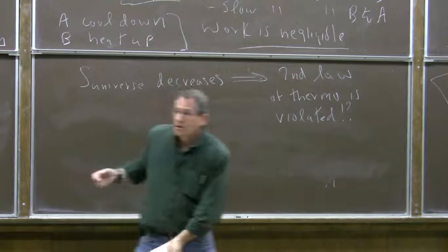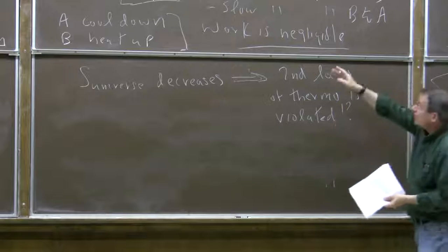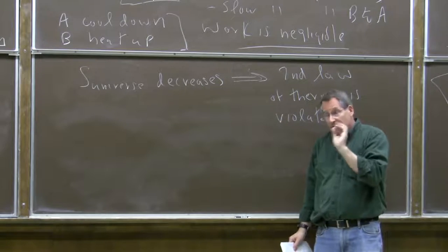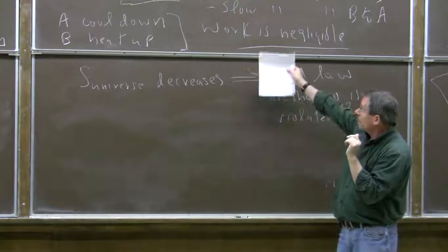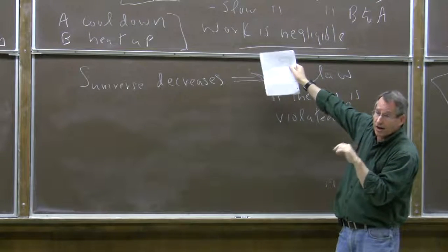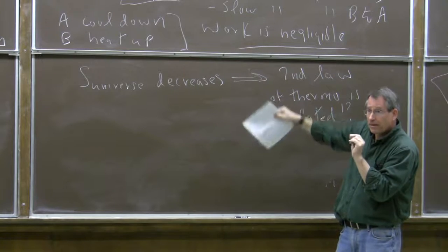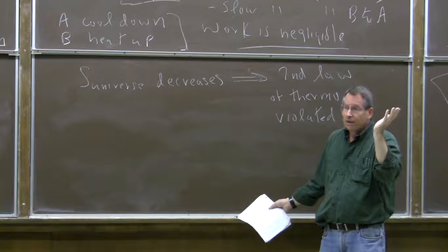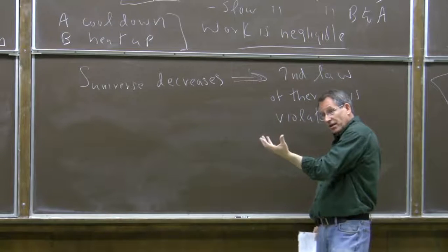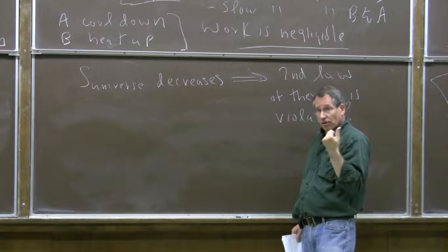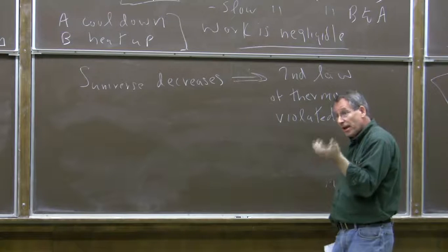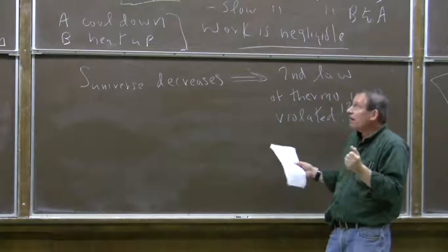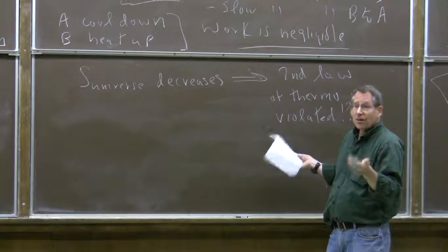Oh, yeah, right. So they're bouncing around, right? Every once in a while, if I keep the door closed, they're going to bounce where the door is. Instead of letting them bounce, I either let them bounce if, coming from one side, they're too hot, or coming from the other side, they're cold. Otherwise, I let them through. That's going to cause some flow of heat from one side to the other, right? One side will get hotter, the other side will get colder. Second law says you shouldn't be able to do that without expending some work. The question is, why is there some unavoidable expenditure of work in this process, if indeed there is?